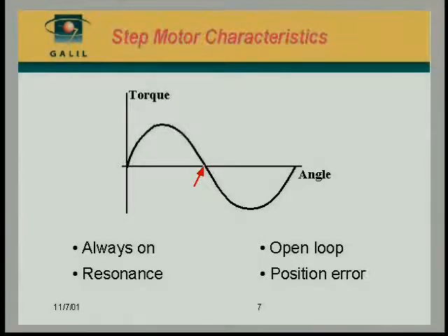Now, in addition to this fundamental resonance frequency, which has to do with the magnetic interaction, a stepper motor has another mode of oscillation, another mode of resonance that's called mid-frequency resonance, and that happens somewhere in the mid-range, like about 1,000 RPM speed. It's a nonlinear phenomenon that is the result of interaction between the driving circuit and the step motor characteristics and so on. It behaves like a black hole. You drive the motor, all of a sudden get sucked into this frequency range where it starts oscillating and loses synchronization altogether.